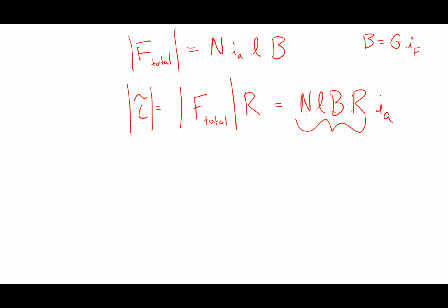So if I'm talking about designing a motor drive, right, if you guys are doing a robot or something like that, you need to figure out how much torque am I going to have to produce? Based on that amount of torque, I need such and such an amount of current. And that tells me how I ultimately design the power supply. Because the power supply, yes, it gives voltage, but it also gives amps, right? So I need to think about the ampacity, or the amperage, that this thing's going to provide. All right. Bottom line to this is I think about the torque.